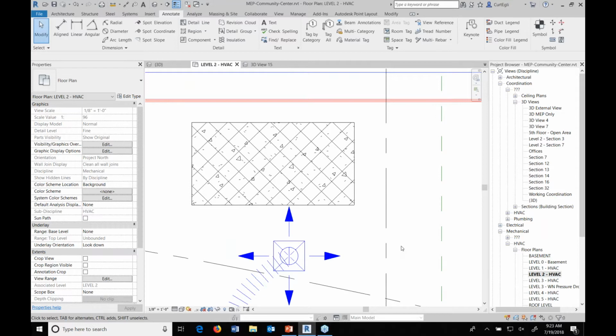A couple of releases ago, they added the ability to stop the upgrade from happening. But it takes a while till that part of the dialog shows up, especially depending on the size of the file, and then it takes a little while for it to back out. So this can help you. You'll see that both with project files and with family files as well.